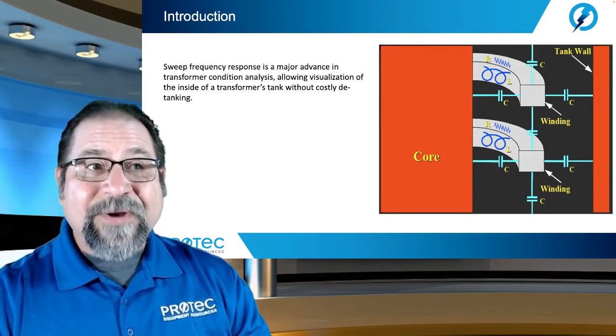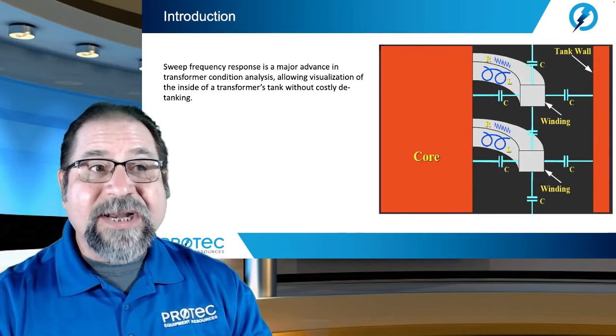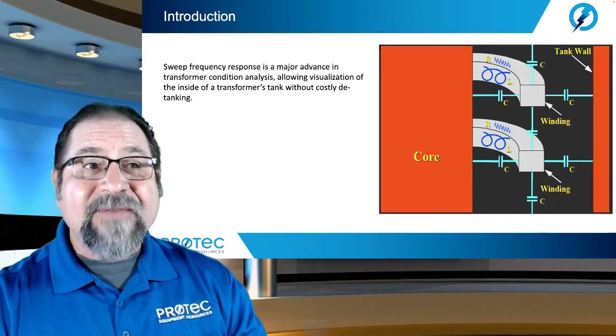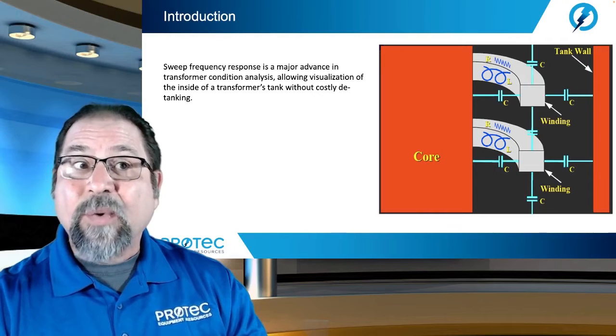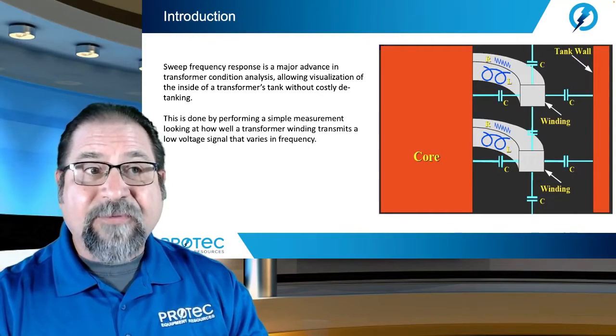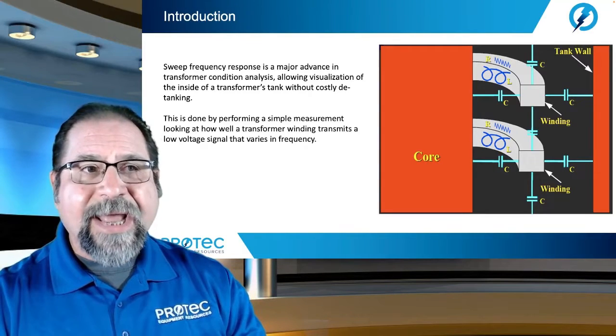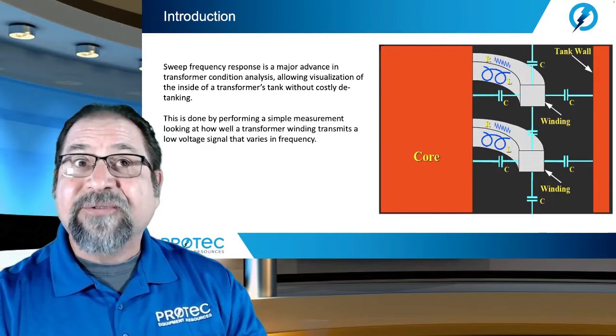Now, sweep frequency response is a major advantage in transformer condition analysis, allowing visualization of the inside of a transformer's tank without costly detanking. This is done by performing a simple measurement, looking at how well a transformer's windings transmit a low voltage signal that varies in frequency.